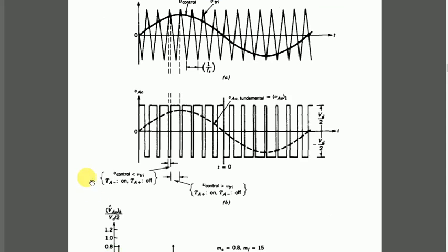Now we can see its comparison here in this first figure. As I have mentioned, in the PWM scheme, or pulse width modulation scheme, for DC-AC converter circuits, we have the comparison of a triangular waveform, represented by this variable, and we can see it has a certain frequency, and the same will be the frequency of the output waveform that we have.